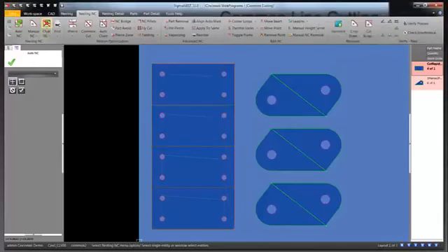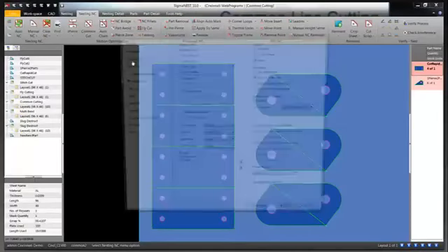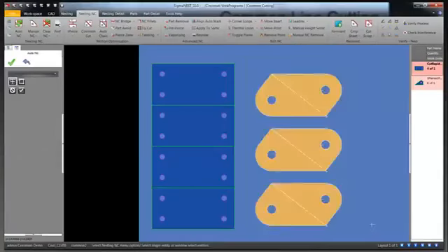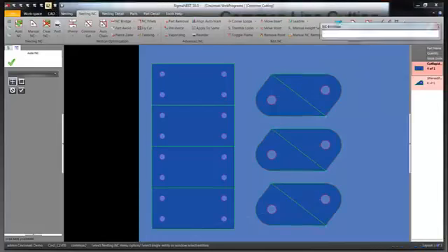So let's go ahead and take a look at the one pierce two parts. On these other parts that we see, in some cases it doesn't lend itself to doing other styles of common line cutting. Just putting one part back to back with another is as good as we're going to get, such as the parts that we see here. You'll see that we're going to cut out both holes, cut straight through the center, and then go clockwise or counterclockwise around the parts depending on where the head sits. Once again, decreasing cut time and increasing throughput on the machine itself.